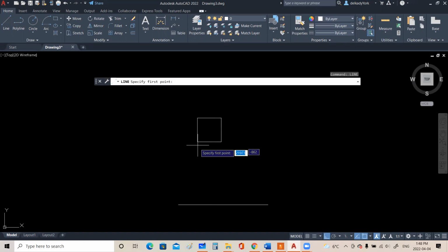Now, when I hover over, there is actually a line that is going to be an imaginary line. I'm not clicking, because if I clicked, I would create a line. I just hovered over, and this is why I clicked on the object snap tracking, because it's going to allow you to snap without actually creating an actual line. And this has to be working in conjunction with the object snap and the extension snap.